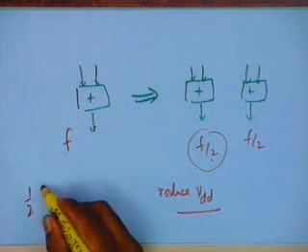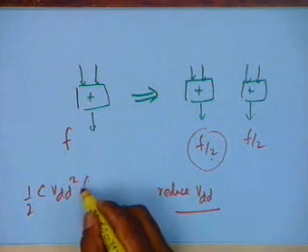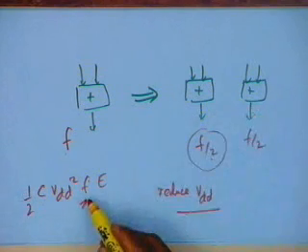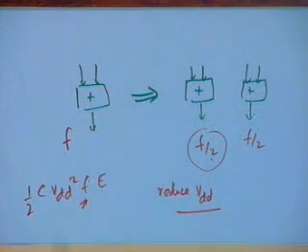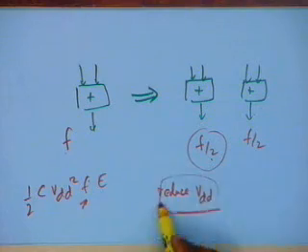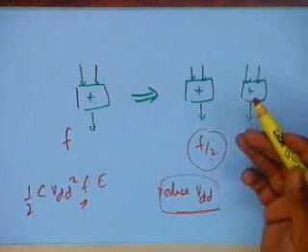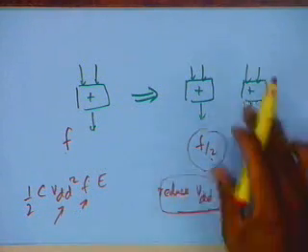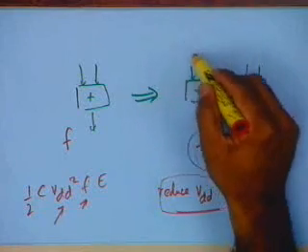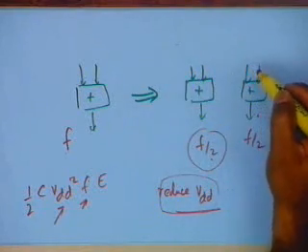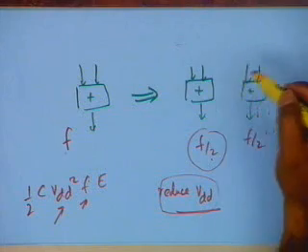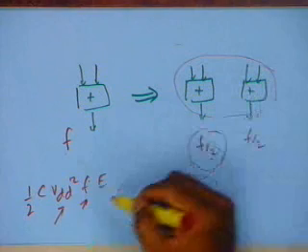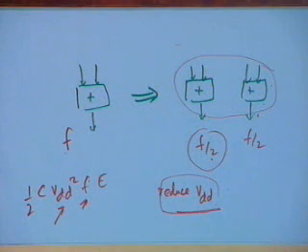After all, the equation that we considered was f times the expected probability. So if I do it for two adders with half the frequency, I won't get any advantage, but I also get an advantage because I can reduce the VDD that the circuit works on, because my delays are lower now, and because of that I will get some advantage in terms of VDD square. One has to account for all the other input and output wiring and so forth, but assuming that those are not substantial, there are situations when such a replacement would actually result in lower power consumption.